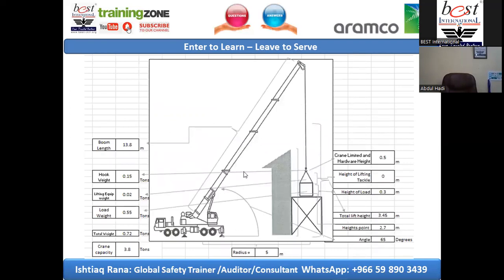Imagine the boom length is 13.8 meters, hook weight is 0.15 tons, lifting equipment is 0.2 tons, so load weight, total weight, crane capacity is 3.8 tons, crane limited and hardware height is 0.5 meter, height of the lifting tackle, height of the load, and make sure you know the total lift height.